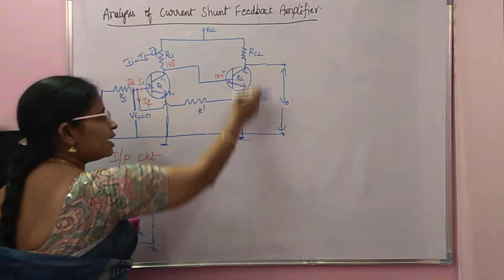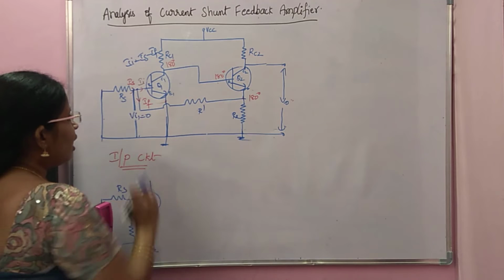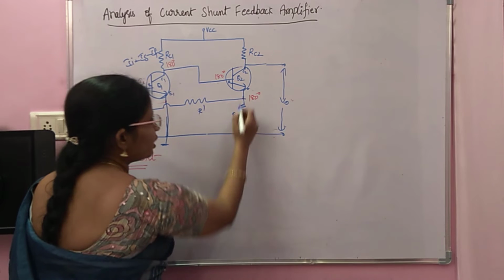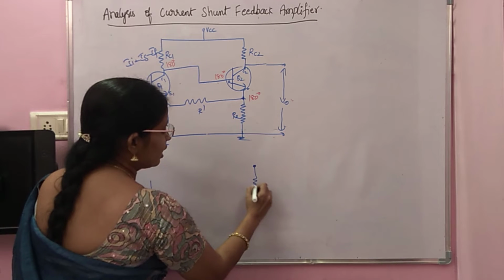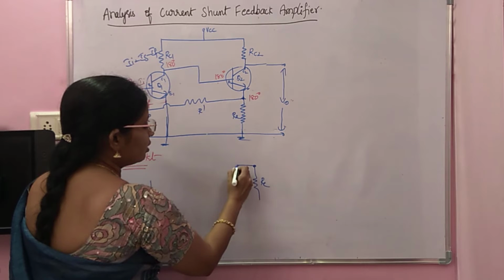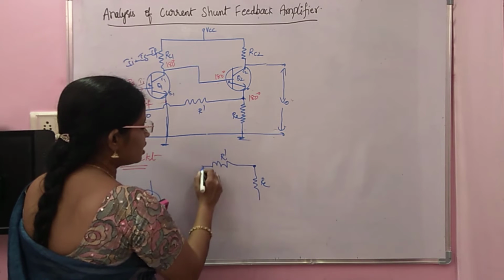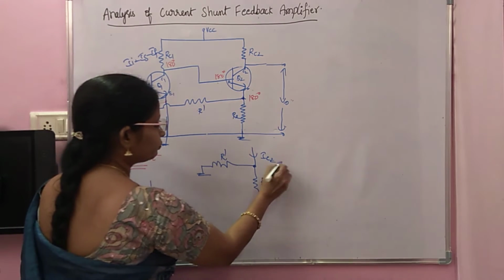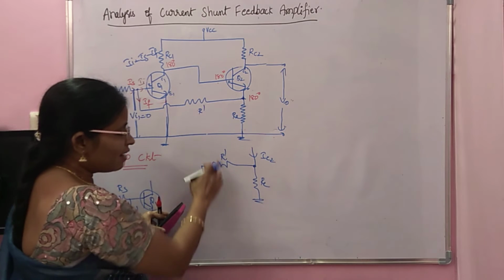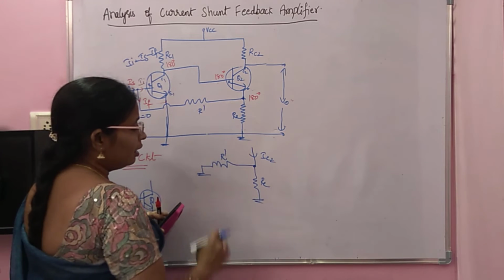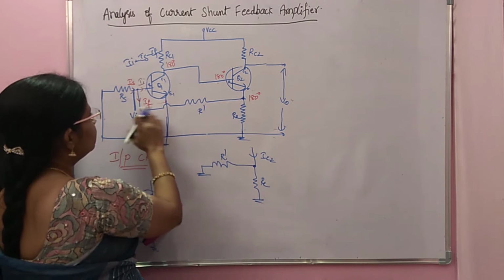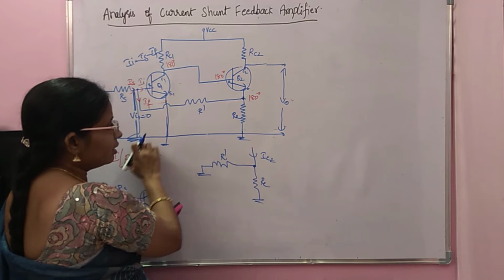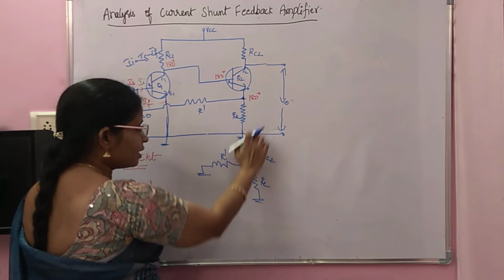Now if you see, your Re and R dash are in parallel, because for Re there is output current and the other end of R dash is grounded. Take this node. This node has this Re, and this is your R dash, which is grounded, and here a current is there, that is IE2. So now R dash and Re seem to be in parallel. The other end of R dash is grounded, so instead of grounding here, we are grounding the other end of R dash here only.